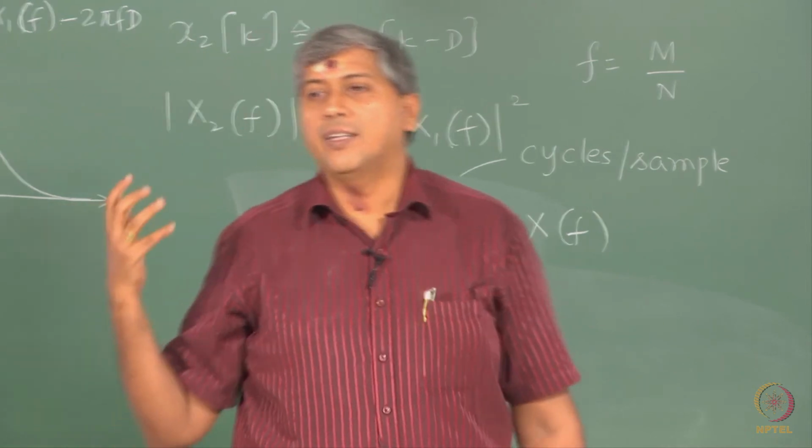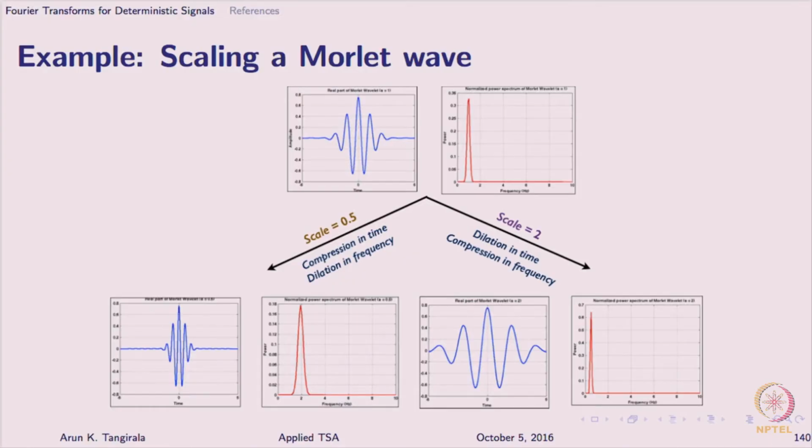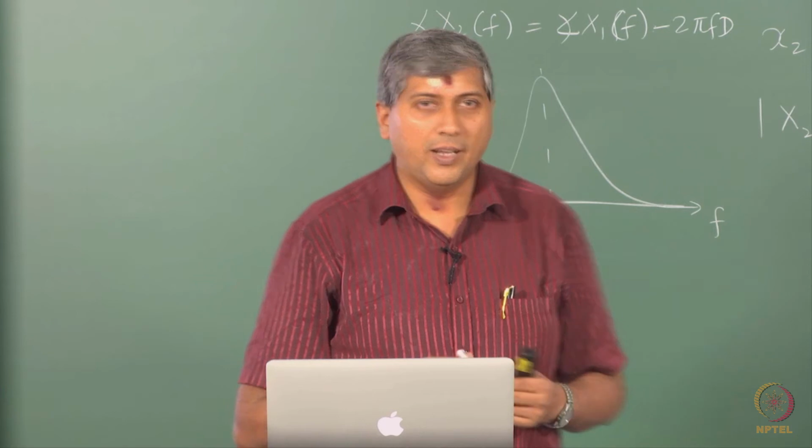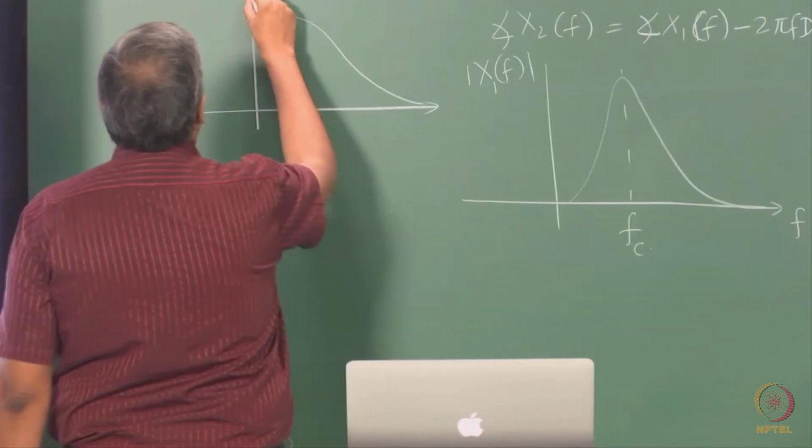And what kind of a filter would the top one be? That is, if a system has a frequency response like that I have shown on the top, what kind of a filter is it? Okay. It is not low pass, it is not high pass. How does the frequency response look for a low pass filter? It should necessarily be non-zero at low frequencies. At 0 frequency it has to be non-zero, right. This is how the frequency response function would look for a low pass filter.